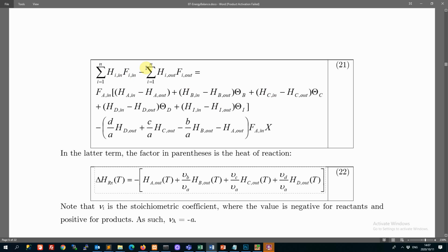And by the way, you might be wondering, I had HI in here and HI out there. Why is it that now you are saying we've got the temperature difference? That's because here, remember, we only grouped out for FA in. We didn't include FA out. So two things were changing here. The enthalpy is different and the molar flow is different, because your molar flow changes as species are disappearing and forming, and so those are different also.